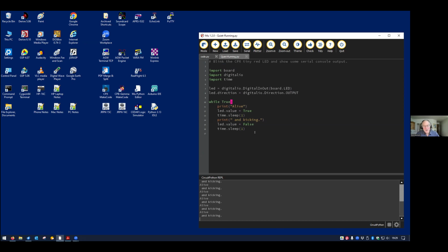The nice thing about Circuit Python, it is an interpreted language. So right now I am communicating on screen, look at the computer, with the Circuit Python. It can do things like mathematics, 2 + 2 = 4. It can execute Python statements real time. So if I say print hi, that's a Python statement. It comes back and says hi. That's going all the way down to the Circuit Python and coming back to the serial port. This is a Circuit Python integrated development environment.